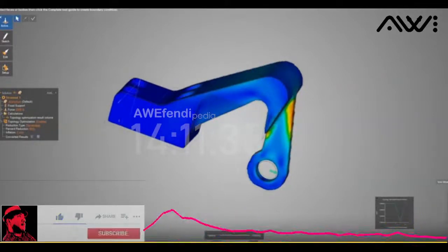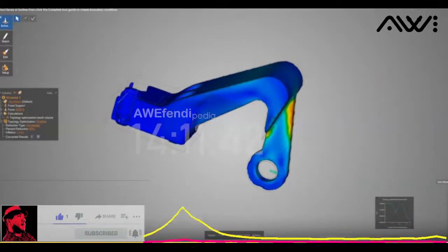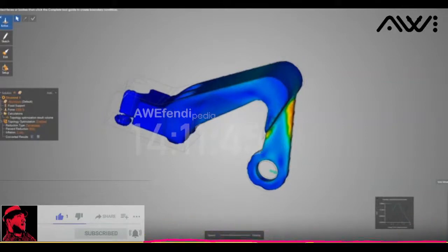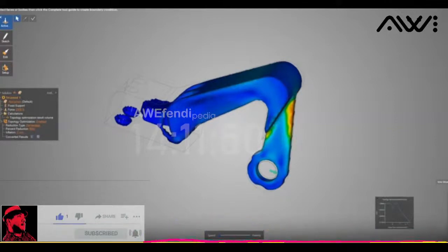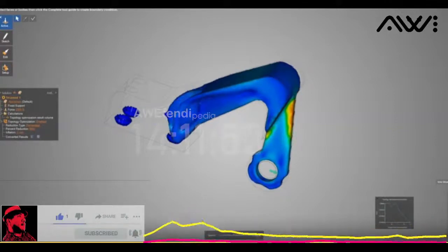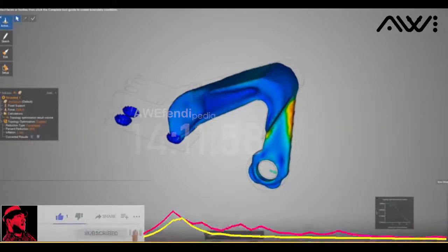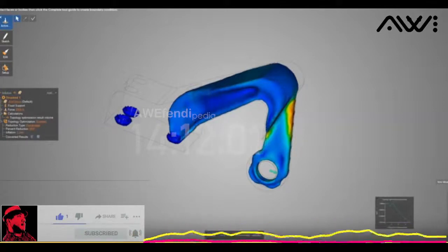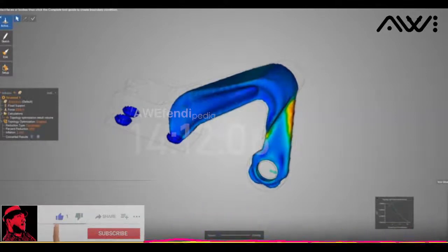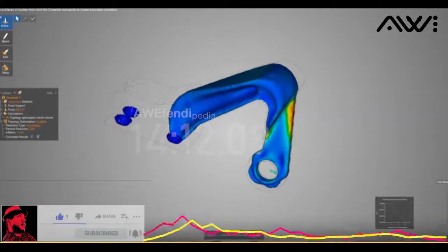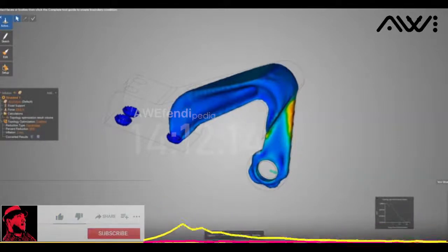But once again, looking at this and saying, hey, look, here we see it's removing that material. Why is that? Why is it doing that? Is it going to keep the 2 front bolts? But from a design standpoint, you need those, because that gets bolted to something else to hold something else down, right? And we've always been in that situation where we need something. Well, based off this design criteria, yeah, you don't need it. But let's say if I start adding multiple load, one going in a vertical area, one going at a 45-degree area, then it will start accounting for those back bolts because I've now added more load cases to it, right?